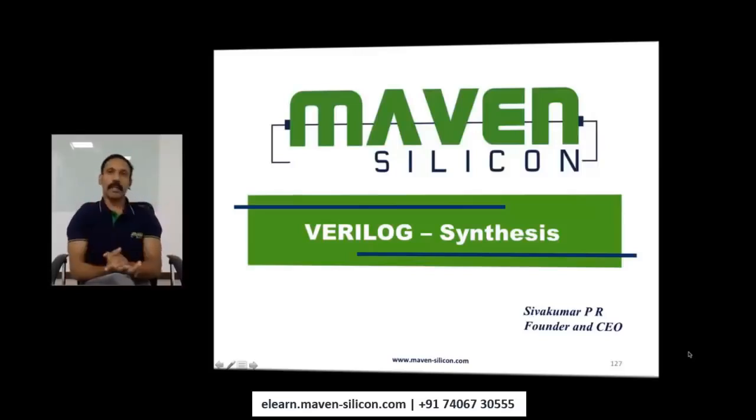Now let's look at the design. That's where synthesis comes into the picture. Whatever source code you have written for the design, eventually it has to be synthesized. So there are some restrictions. You cannot use all constructs in the language; you have to use only the synthesizable subset. You need to understand the common synthesizable subset that can be used across various tools in the market.